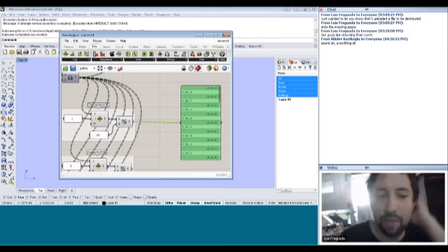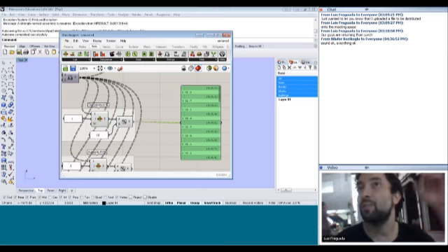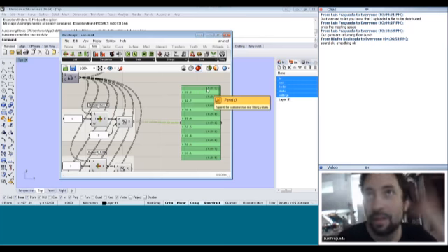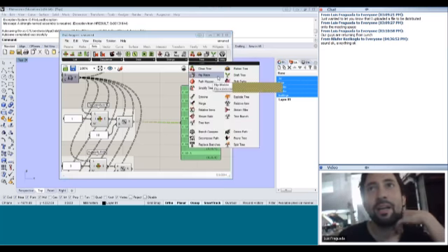To do this, we can do it several ways. We're going to do what's called flattening. We're going to flatten the list. We're going to take all of this other branch logic. A branch is one of the lists in the tree. There's a lot of different names for this kind of stuff. So what I'm going to do is go to Sets, Tree, and Flatten Tree.